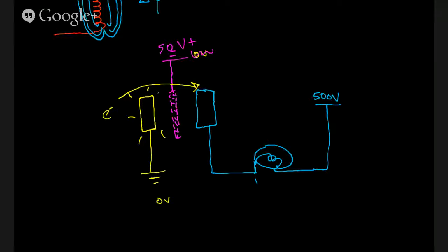If we give it a path for the electrons to follow, instead of conducting to the anode, they're going to be shunted away by our control grid. I have to keep making sure there's no messages in there. So this is our basic, we've created, instead of a diode, what we call a triode.